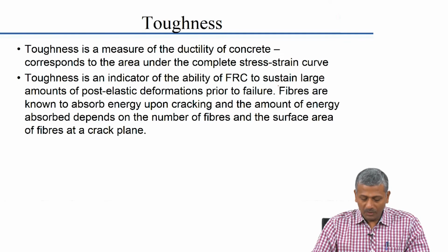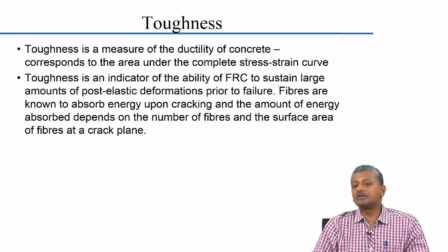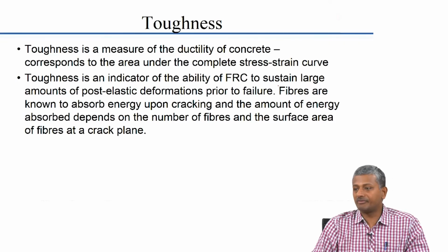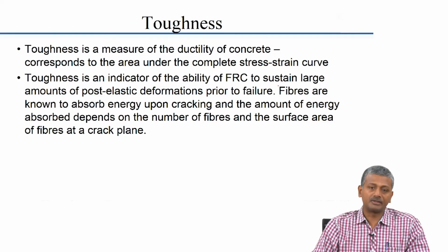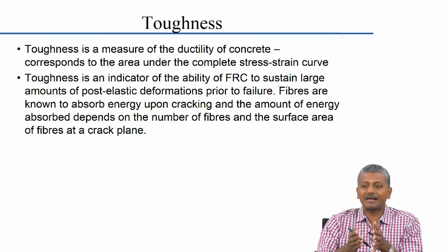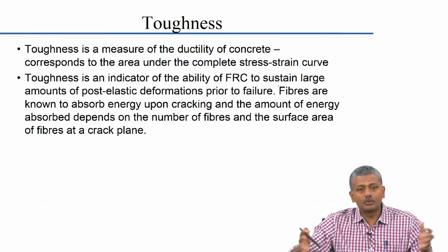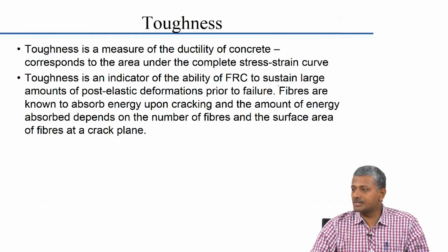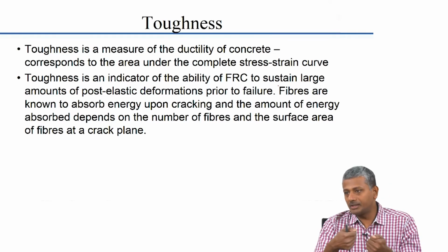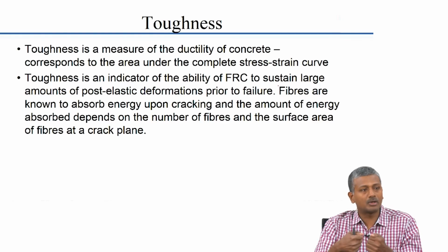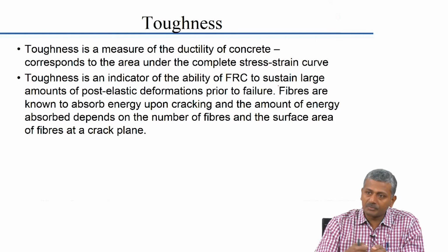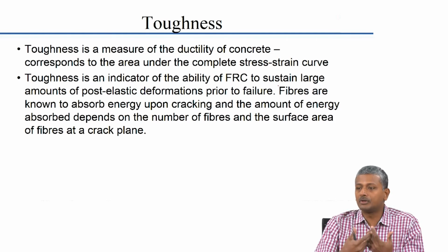Now, what we have to get at as far as fiber reinforced concrete is concerned is not just the capacity that the material has before it fails, but also the amount of energy that can be absorbed by this failure. In plain concrete, once a crack initiates, it rapidly propagates towards failure. But in fiber reinforced concrete, as we have discussed earlier, the cracks open up gradually, because the fibers are bridging the cracks. They do not allow the cracks to open up very fast. And because of the presence of fibers, a lot of energy can be absorbed during failure.